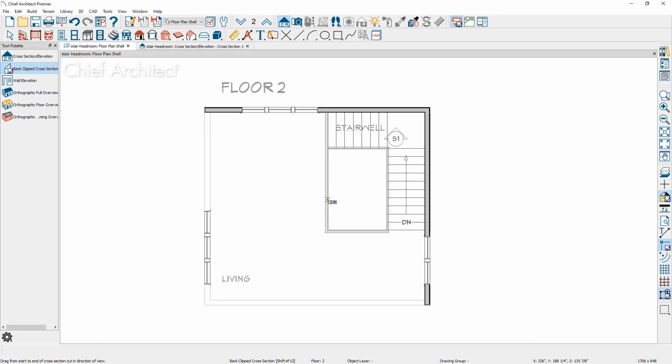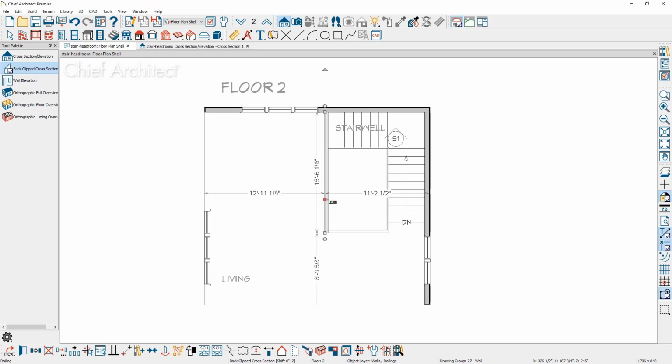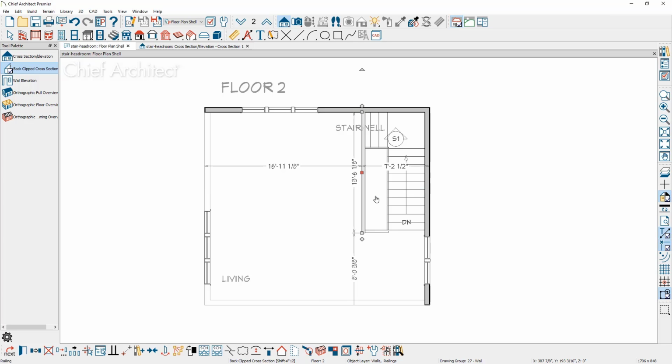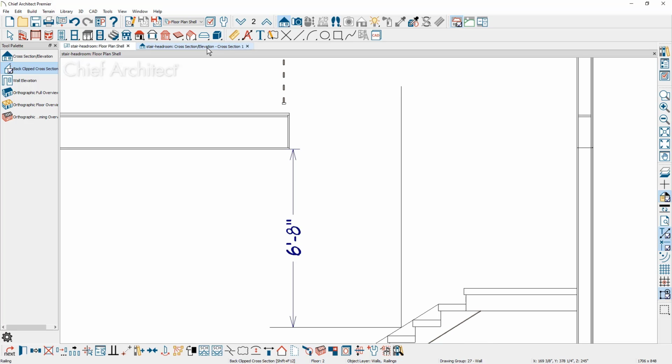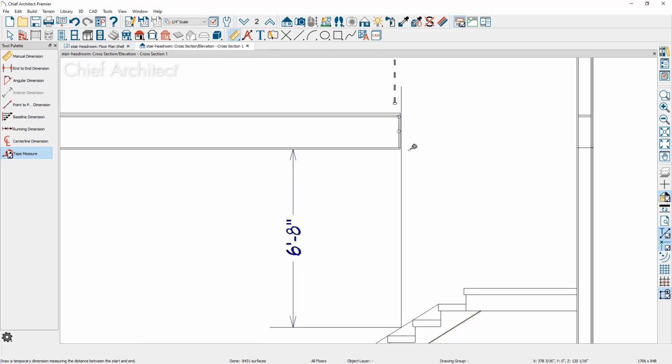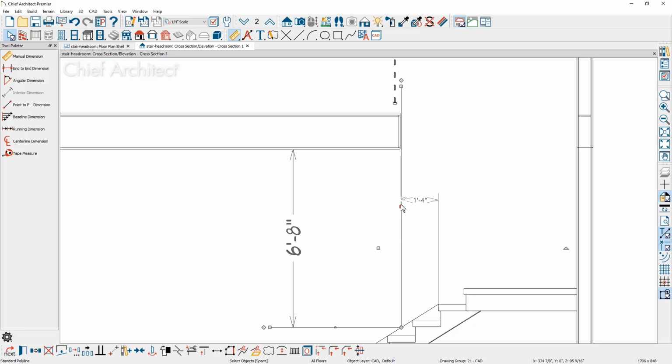I'm going to click on this wall. If you have your temporary dimensions on, you can click on the railing wall, and in this case I'm going to take the dimension. I'm going to go minus 4 feet. That'll give me about a half inch buffer and still meet that headroom. Let's go back in and take a look at that section view, and you can see that I now meet the headroom. This line that we drew temporarily can be removed.